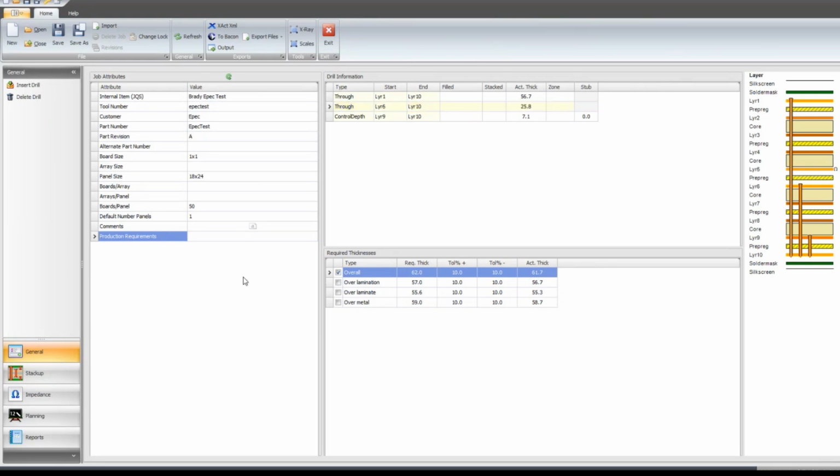There's a lot more on the planning side, but one of the important ones is the automatic math for thickness and for drill validation. So it helps prevent some user errors like specifying an invalid drill to the types of layers that they're in, or there's some size validation that we do in different parts of it. We can't have a microvia that's 20 mils. It will also drive other logic and the planning processes in CAM and in other places.